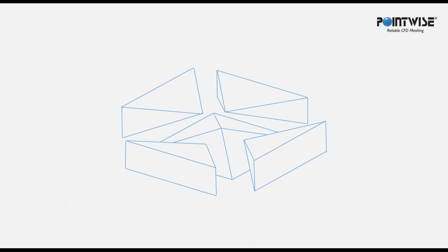So let's go ahead and open up the presentation again. The way you would expose triangles from a quad is you need pyramids. So here's a base pyramid that would sit on top of a quad, and here are 4 surrounding pyramids that expose 4 triangular faces. Now all of these elements together can be combined into a single hex after the fact, but this topology exposes 4 triangular faces.